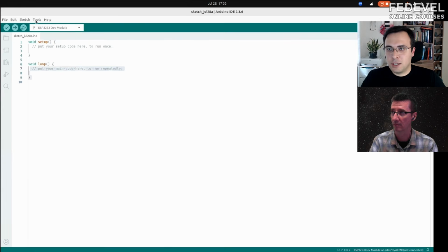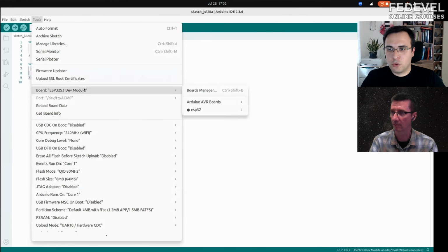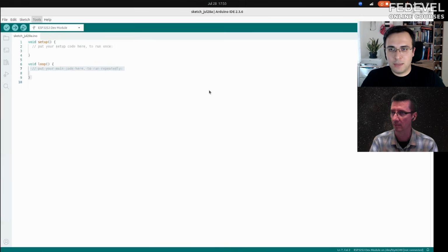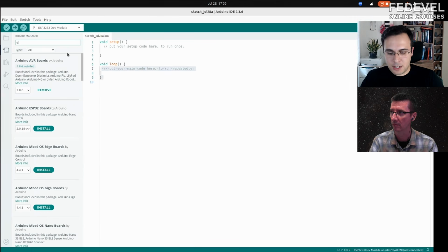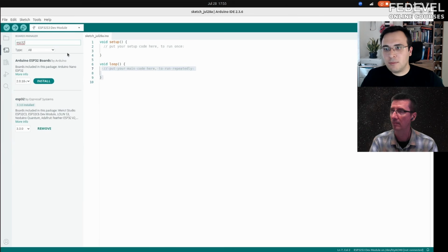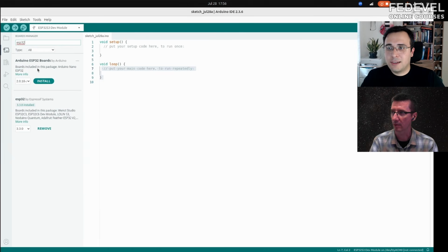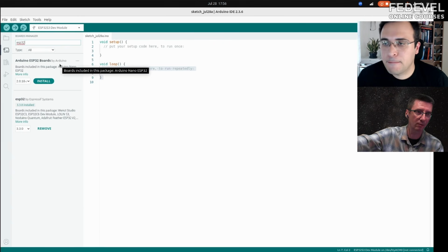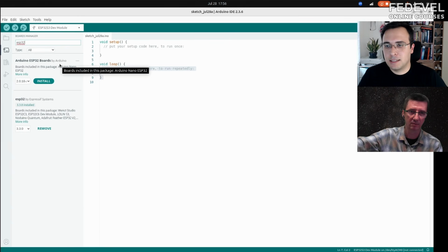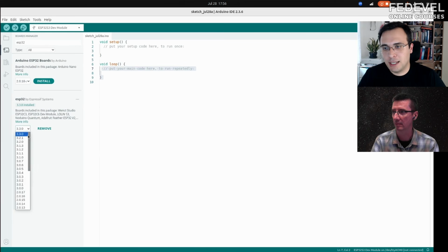Once you press OK, you need to go to the board manager. So you go to Board and then Board Manager, and you can search here for ESP32. I've already installed this one, but once you search for it, this is the ESP32 by Espressif Systems. It is the SDK that ESP32 officially releases, from the link we just inserted there. You have to download the latest release.